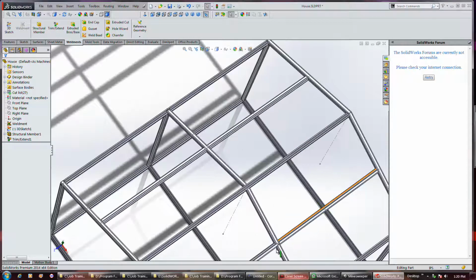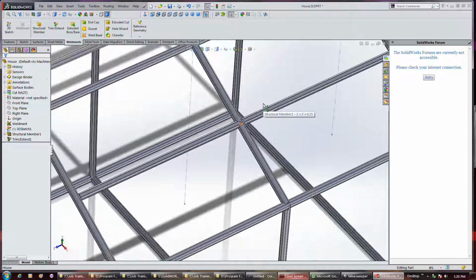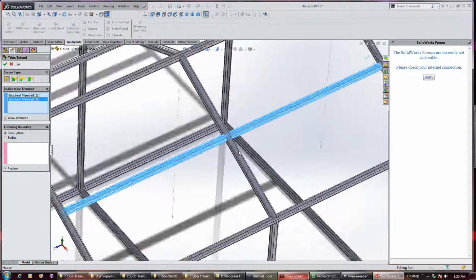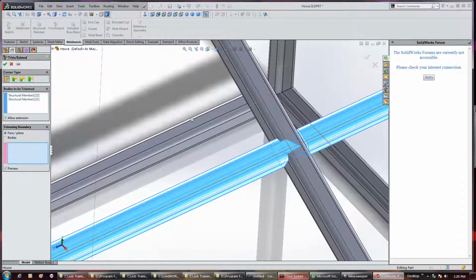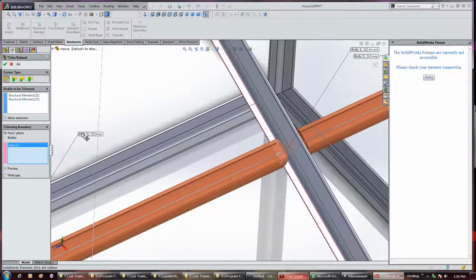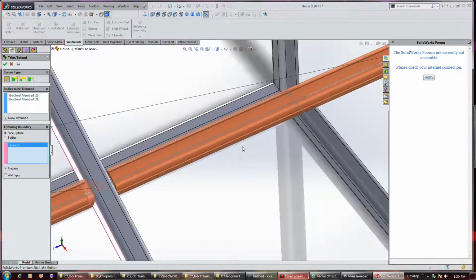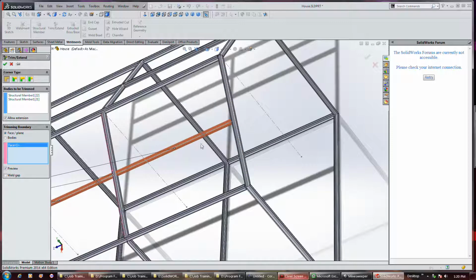Okay, now before, we noticed we got these little weird sections in here, but that can actually be edited with the trim extend command. And you can edit multiple of these at a time, but I think they still have to be related to each other in a particular way. But you select the body, then you look for a trim body, and we have to set this to face instead of body. Oh shit. Boy, this thing gets even more annoying when you're in this mode.